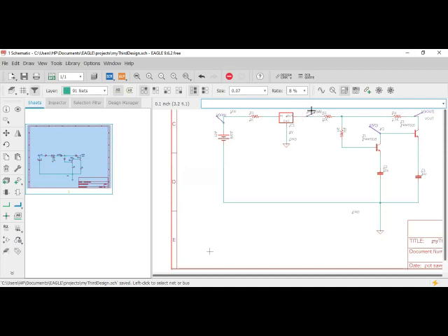So we want to check the voltage that comes out of this voltage regulator. That's why we're adding a probe here. And here, we want to know the voltage that enters as the input for this transistor. We want to check the overall output voltage. So you save these. Then the next thing is to simulate these.